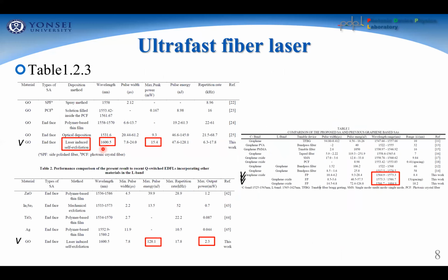We made the longest wavelengths in the L band, and the maximum peak power we got, and we also have some high pulse energies and maximum output powers. We also compared different materials based on the C and L band, and we also have tunable wavelengths from the C band to the L band, and even dual wavelengths we also achieved.